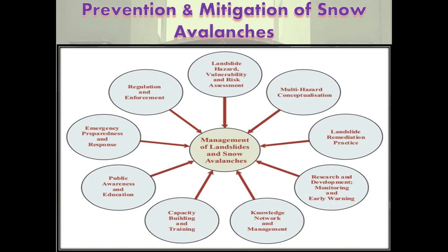are examples of this. Second one is deflecting structures in the run-out zone to keep the moving snow of an avalanche away from critical locations. These are massive structures usually made of earth, rock, or concrete located in or near the avalanche track or run-out zone. Third one is retarding structures, usually earth mounds or large concrete structures called breakers or tripods.